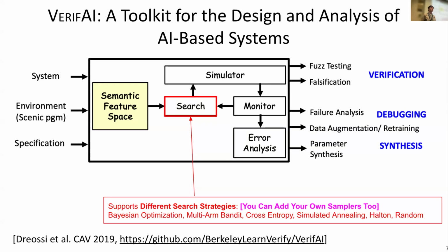What I think Eddie was alluding to is there's a limitation of the current setup in VerifAI, whereby you can't use VerifAI range and those other external parameters inside behaviors. Right, so they can only be parameters sampled at the start of the simulation, not all the way through. That's because some of the VerifAI samplers expect the feature space to be known ahead of time. I think we might have talked about this last night. We have some ideas for extending that, but there's a current limitation.